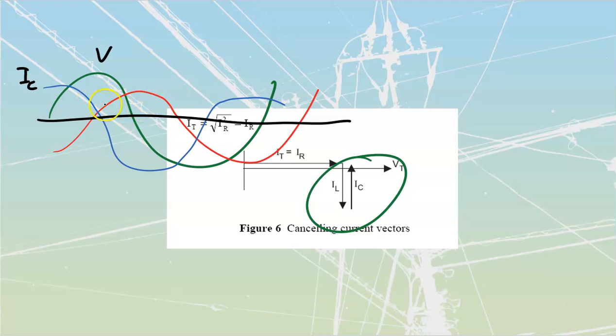And we see that by the time my voltage has risen, this one over here is going to be lagging that quite a bit. Therefore, this is going to be my IL. So what we should see, if I had drawn these much better, is that my inductive current is in the negative, while my capacitive current is in a positive. And then over here, once again a poor crossing that I've drawn, I would see that my inductive current would be at a maximum, while my capacitive current would be at a maximum in the opposite direction, and both of them would cancel out and cross over here.